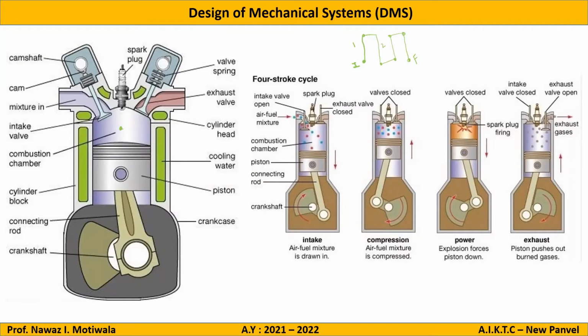So now again, the question goes to you only. Sir, first of all, the air fuel mixture is going inside with the help of one intake valve. Then it closes. Then compression will happen. Then the internal energy, that is the temperature, will rise, and there will be some reactions. After that, the power stroke will happen and the piston will go down, then the exhaust valve will be open, and then the cycle will repeat again. Perfect, good answer. Very good answer.